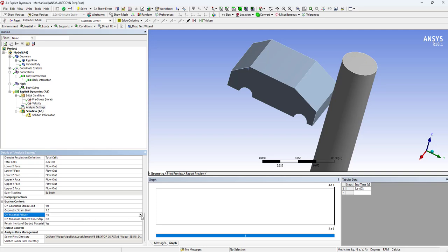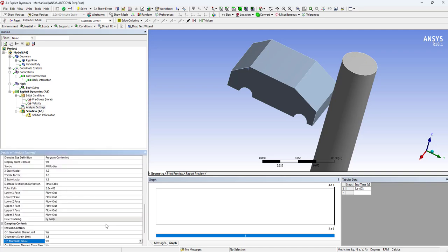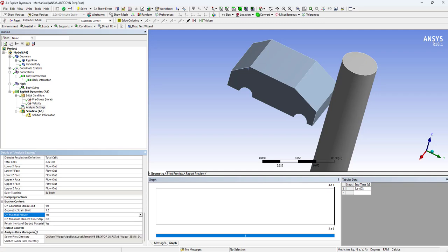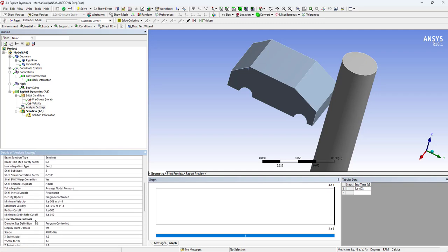Or here in this case, we want the material to tear apart. If the strain reaches 75%, I'll just change this to yes. So when the material fails under plastic deformation, the mesh elements need to disappear. So these are the general settings that we can set for now